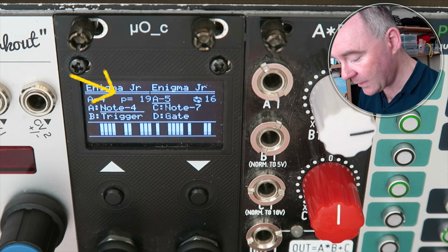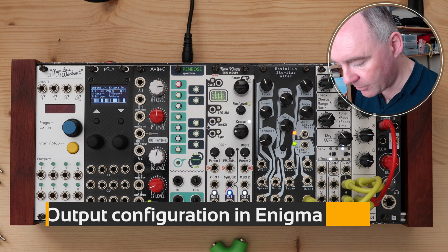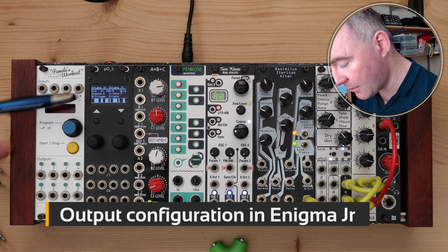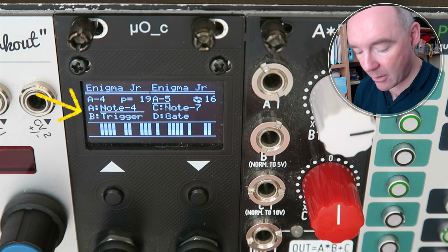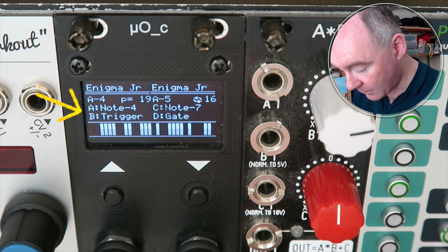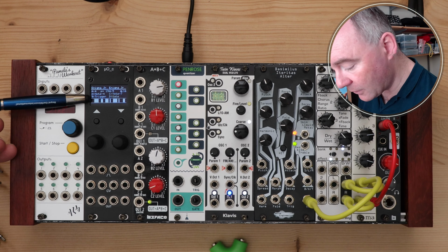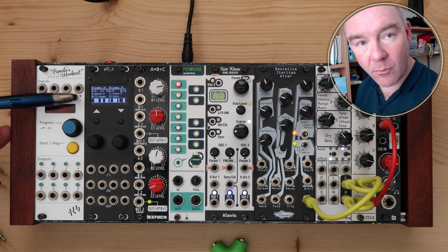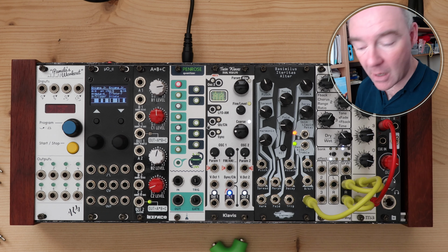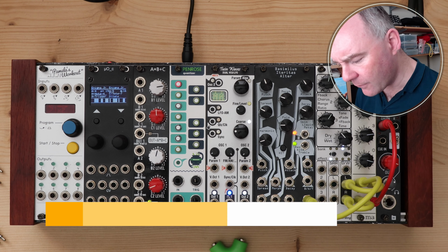You change that. And now we come to the two output parameter definitions, the A and B here, like you see on the screen. This allows you to specify what output A does and output B, or of course output C and D if you're in the right hemisphere. Output A is note 4 and output B is trigger. What trigger means is whenever there's a 1 value at bit 0 of the shift register, a new trigger gets generated. But what does note 4 mean?